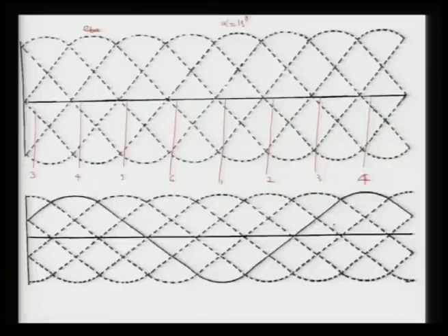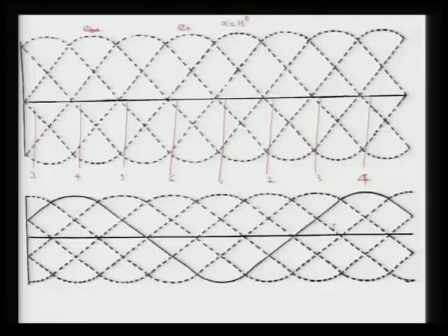So, now we have to write the line voltage as usual practice. So, it is EBA, here it is ECB, good, here it is EAC, here it is EBA, and now this voltage will be ECA, this voltage is EBC, this which is left out, this voltage is EAB, this voltage is EBC. Okay. Now, you can see when 6 and 1 are conducting, what will be the output voltage.